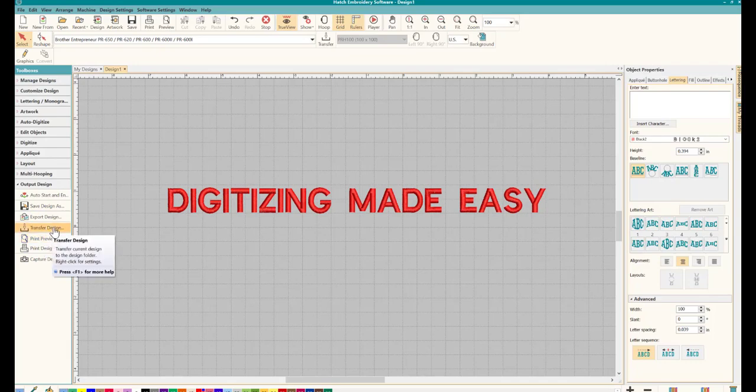Now that's used if you have your machine plugged into your computer that you're using to digitize on, or you can export design. But first, before we export it, right now it's saved as an EMB file, which is your native file, which gives you all of your editing things. So before we can export it, we have to know where we're going to export it to. And the easiest way of doing it is just simply by plugging in your zip drive or USB disk.